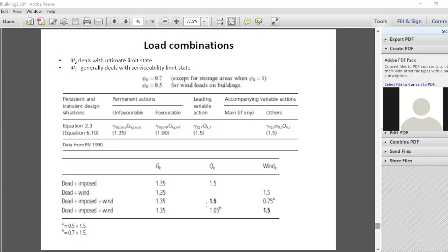When you assess the values based on probability, you'll find that when the building is fully loaded, the chances of a cyclone hitting can be less. So the impact of the cyclone we consider as 75% of the maximum value.